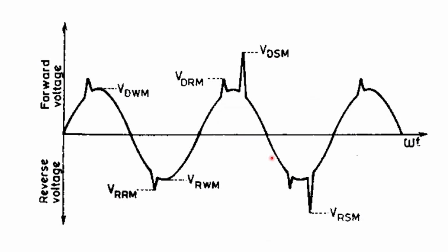Okay, similarly there will be two other terms. One is the VT and one will be your dV/dt term. Okay, so VT is the minimum voltage that appears across the thyristor, or that is the on state voltage drop of the thyristor. Okay, when the thyristor is in conduction state, and this VT will depend upon the current flowing through the thyristor as well, as we discussed yesterday.